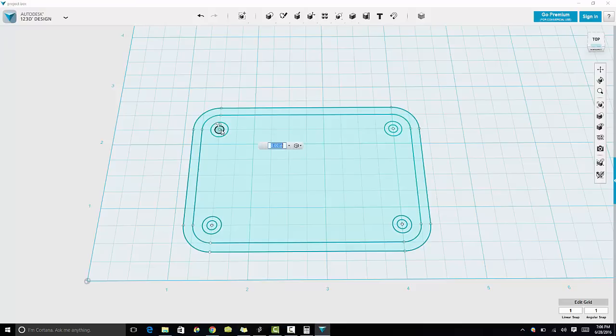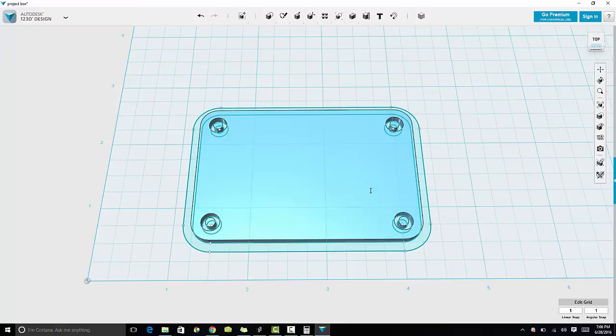In extrude, all we need to do is click on everything we want to add the third dimension to, or anything we want to give height, or Z, however you want to call it. So I clicked on everything, the inner circles and the inner shape here. And I'm going to add a Z height of 1/8 inch. No surprise there, I don't think, right?